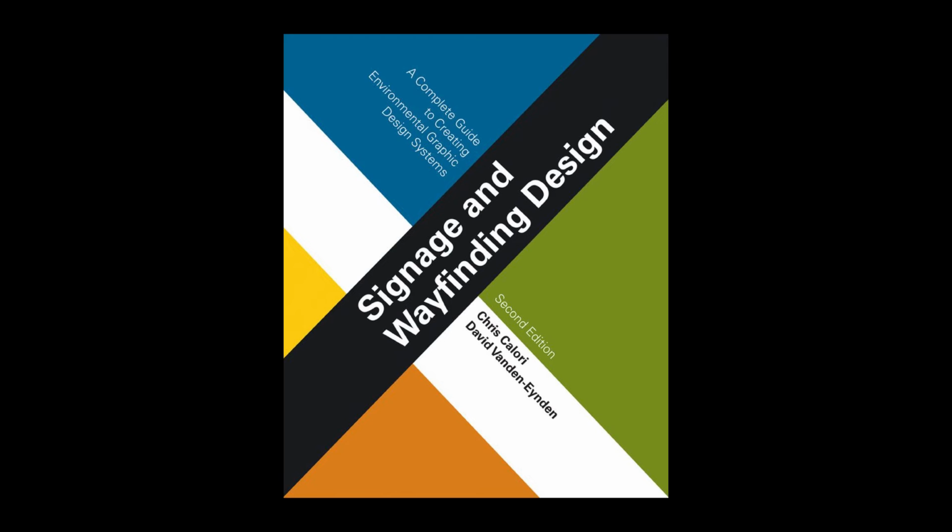Large freestanding glass signs can be self-supporting if made from several sheets of glass that are laminated together. Although laminated edges should be protected from the elements on exterior signs, also, many glass suppliers can provide graphics on the lamination interlayer as well as manipulate the interlayer's color, texture, and opacity.